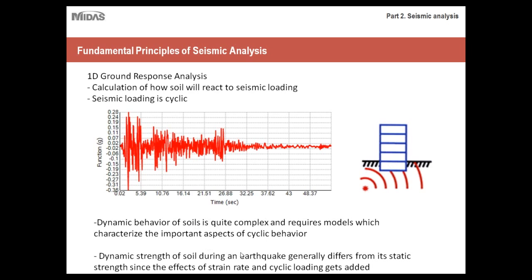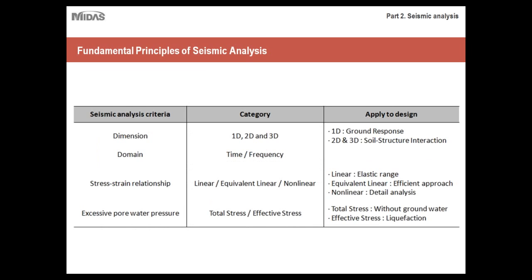And the dynamic strength of soil during an earthquake generally differs from its static strength, since the effects of strain rate and cyclic loading get added as well. So just keep in mind that the way soil reacts to seismic loading is very unique, and static and typical live loads wouldn't be able to account for that.